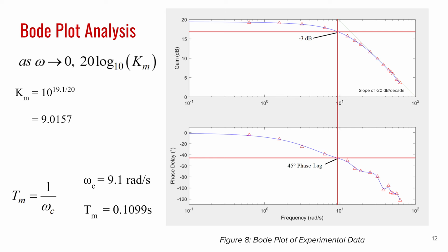The frequency domain analysis is useful because it allows us to see the relationship between input frequency and output gain. By using this frequency domain, we are able to identify the cutoff frequency of our system. This is not possible to do in the time domain analysis and is important because after the cutoff frequency, the gain will begin to decrease very rapidly, which limits the amount of usable frequencies for our system.